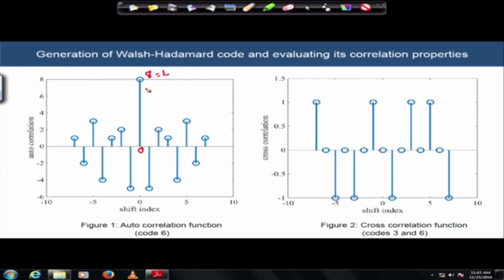On the other hand, sometimes it is also desirable to have a high value of autocorrelation at 0 and a reasonably high value just after 0 as well, because in cases of loss of synchronization, the second value also is important in order to detect the signal and synchronize it. Nevertheless, usually the case is that we need a very high autocorrelation at 0 lag and low values around it on the positive and negative side.